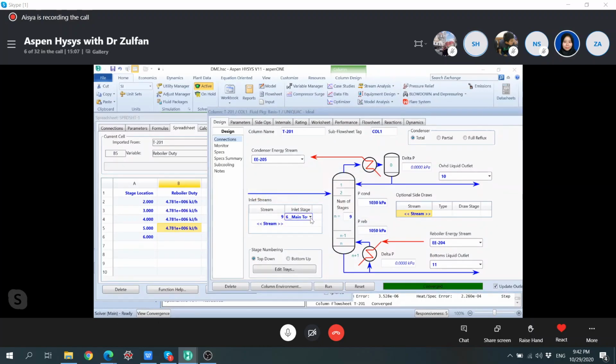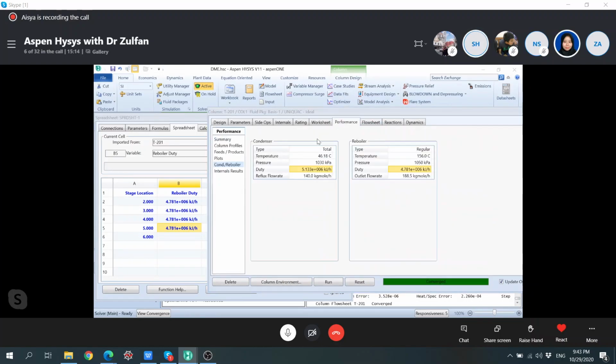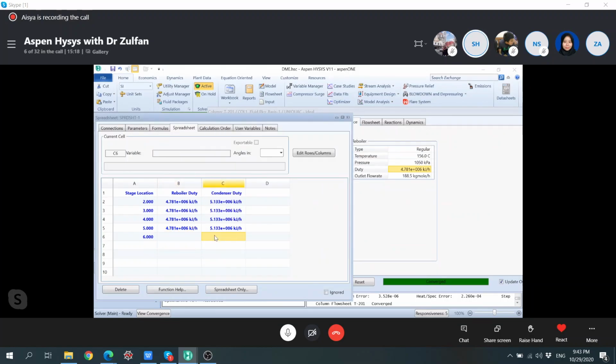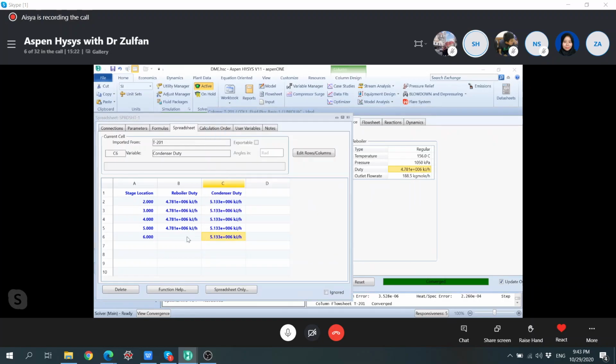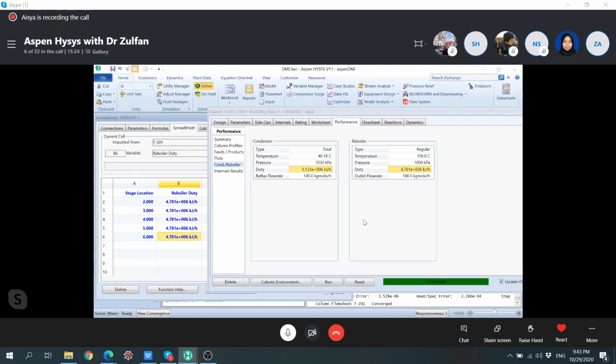It's just that the pressure is not really okay, but in terms of mass balance, it's fine. We cannot use this if you want to do a dynamic simulation, you cannot start with this feed stage unless you increase the feed pressure. There's not much difference in this value.